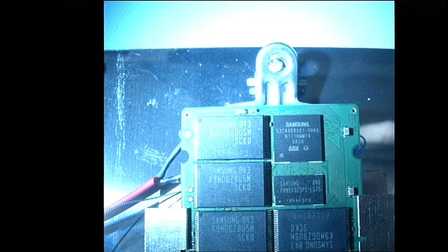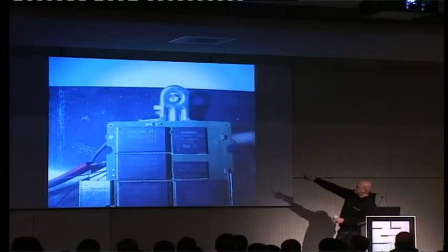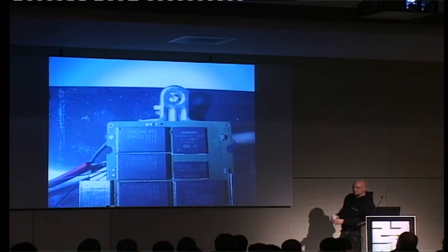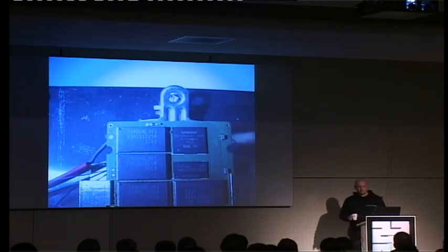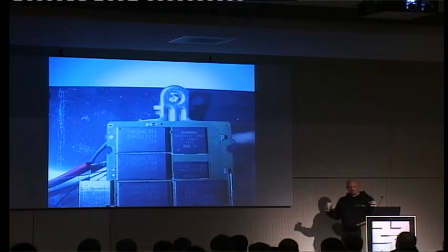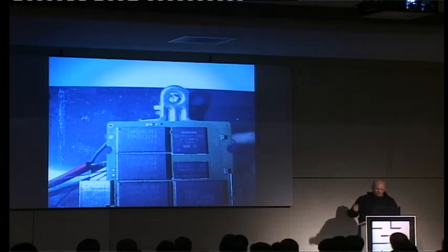You've got a whole lot of flash chips. They continue on the other side, on the back side of the board. You've got the controller, which is a complete computer, and you've got the cache RAM chip here that is necessary to quickly do the blocking, because of course a flash drive can't write any bit it gets. It has to aggregate a page before it writes it back into the memory, because otherwise it would wear the memory too much. Anyway.